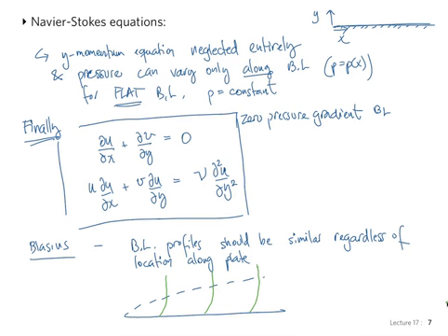All that happens as you move along the boundary layer is that things get a little stretched out as delta increases, delta being the thickness of the boundary layer. This is here the level of delta. So this argument means that the relationship between the actual velocity of the fluid and the free stream velocity is a function, an unknown function, call it g, of y over delta. So you can non-dimensionalize the problem. G is still an unknown function, but these are dimensionless variables now.